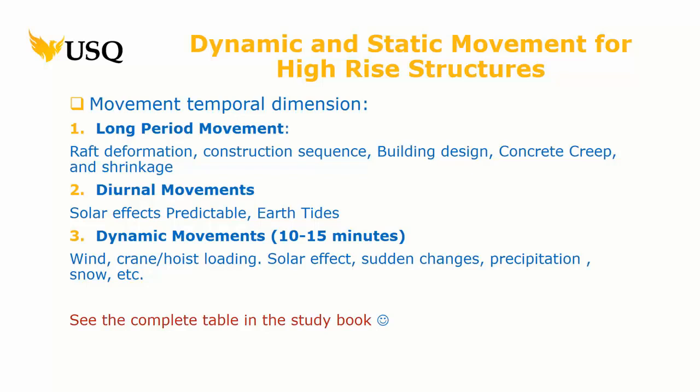The diurnal movements, you should know now that diurnal means the daily movements, right? There's quite a few of them. The biggest one is sun. Now, when the sun hits the building here, which is coming up in the east, to my right, when it rises in the morning, that side of the building heats up. This side of the building remains cool. It's still warming up with the air, but not to the same effect. This is a sixth floor building. The impact is relatively small, right?